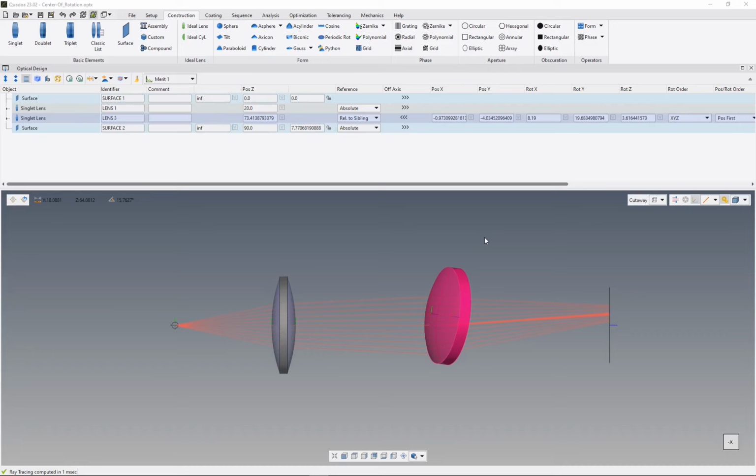In this video, I will show you that it is very easy to convert any position definitions and dependency definition of the elements even after the complete setup of the optical system. For example, it is possible to convert between the option if this lens highlighted in red is positioned relative to the first lens or absolute to the global coordinate system, or maybe the lenses are stacked on each other in the same mounting and so on.